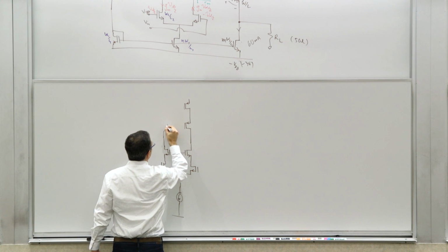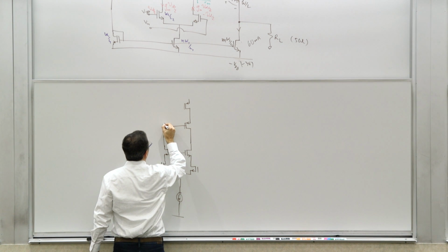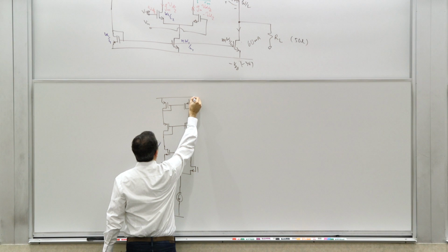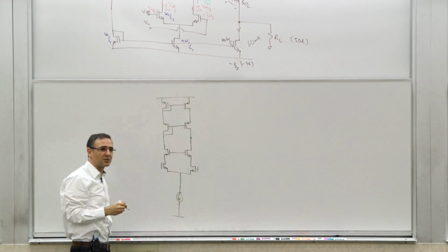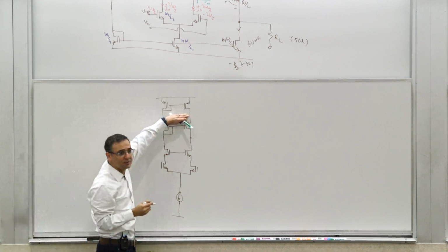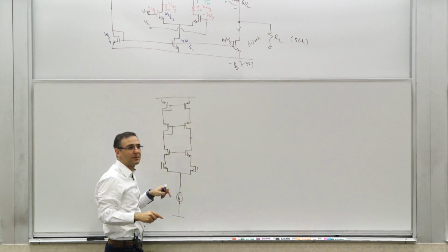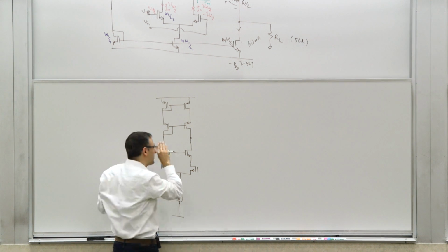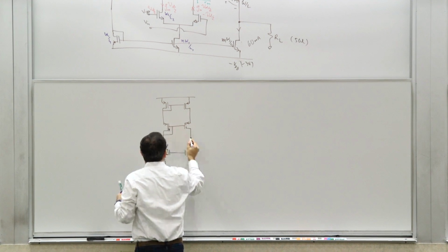And if you are trying to get your single-ended output from this stage itself, you can do something like that. So you have a cascode current mirror. These upper 4 transistors are a cascode current mirror, right? It's just a better current mirror. These top 2 just make it a better current mirror because it has a higher output resistance and better matching. Of the force, matching is not the right word. It actually forces the two currents to be better matched or more equal.